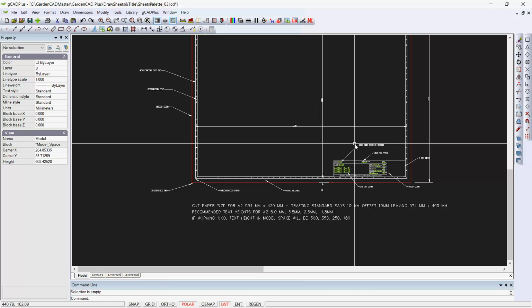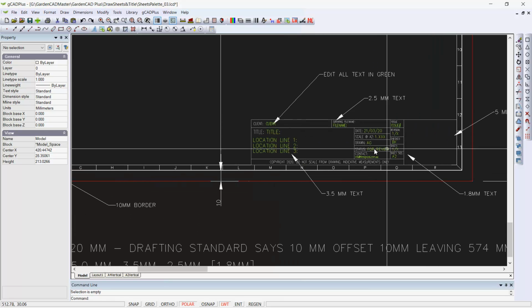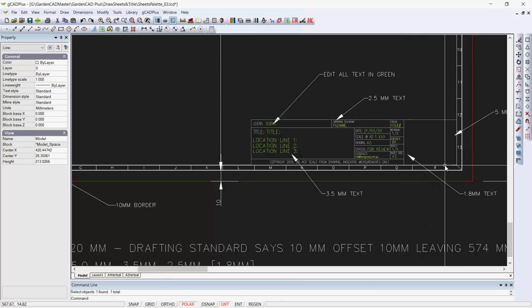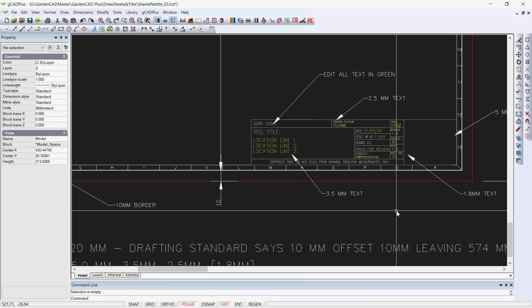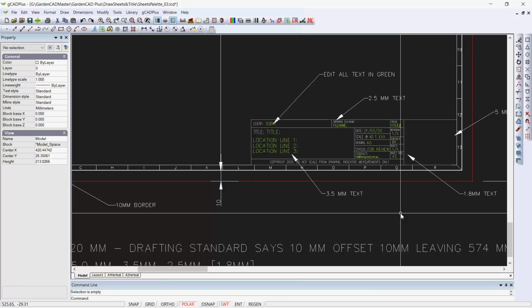It'll be very useful in doing designs for large broad scale and corporate work. If you're working in residential design, you might want to do away with a lot of this information and just do a very compact title block in the corner of your sheet, and perhaps have this sort of information hidden on a layer that you can then hide. So I hope that helps just a little in understanding how title block information has to be set up in some instances.